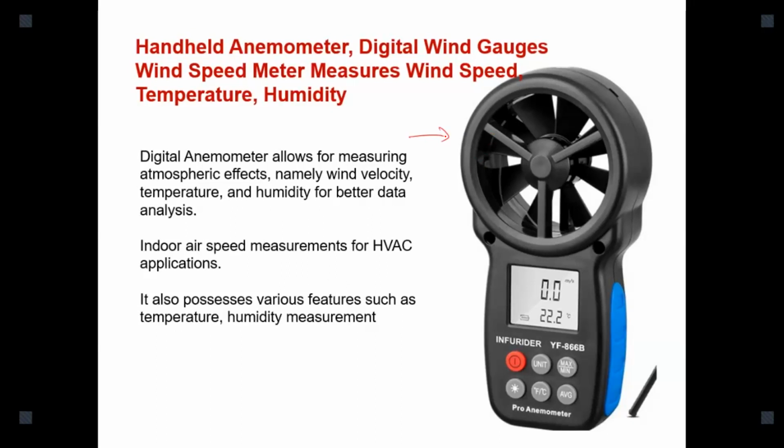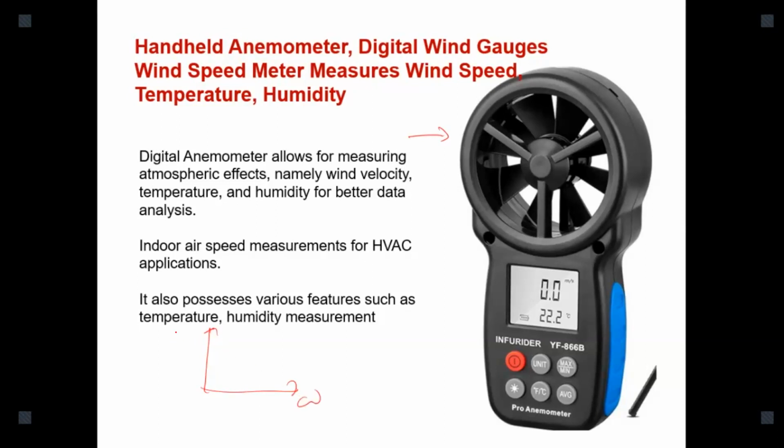This is because it is a propeller type; there's a fan. The disadvantage is that the propeller RPM is not directly proportional to the wind speed. There's a curve because of the rotation, so it needs to be calibrated properly. It is not like a cup anemometer. Here there's an aerofoil, and its shape and everything depend on the RPM and the wind speed, so these need to be calibrated. It is already calibrated, but needs to be calibrated point to point. These are different applications; in most cases this type of instrument is used for indoor applications, not for energy applications.